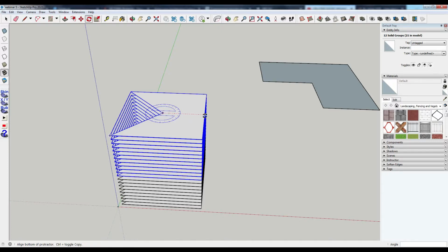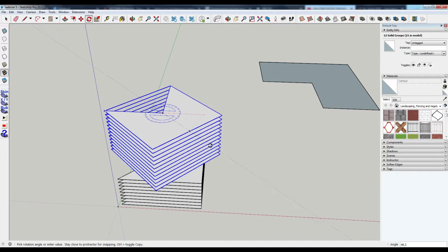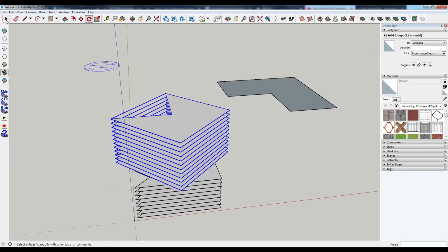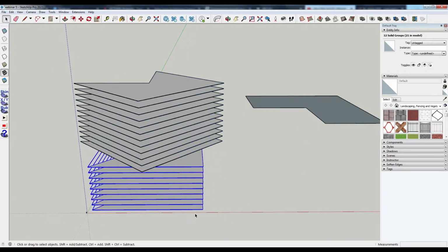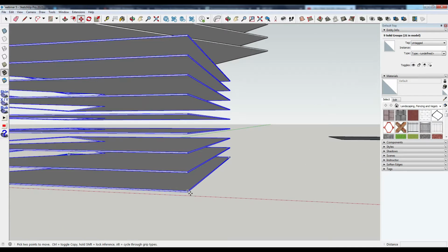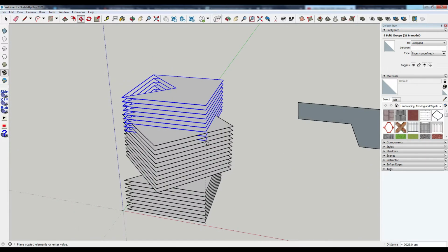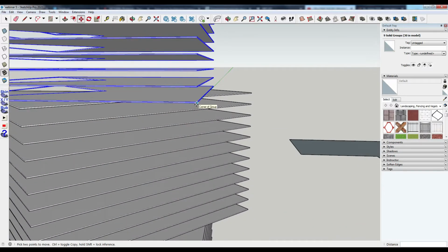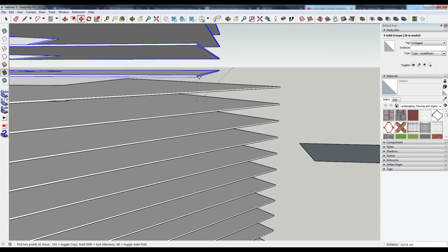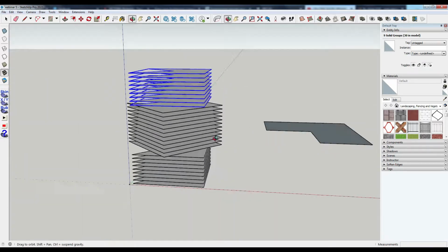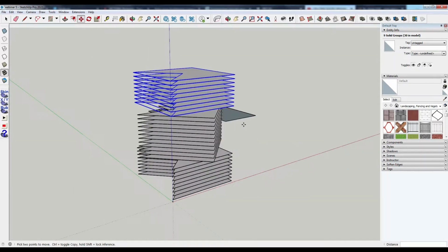I will now select some of them and will rotate them. I will make a copy of the first ones. I will align them first and then I will make the height of the standard floor. Pay attention that we always use an accurate point, not just using the move tool with some random part of the element.